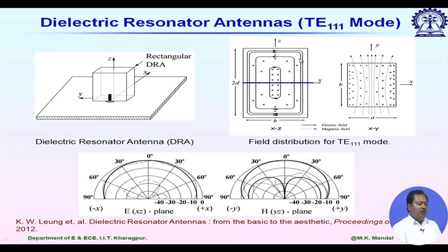Now, if I consider a full resonator, the ground plane is placed in the middle. For this full resonator, look at the electric field plot. It looks like one loop. Z is the top direction, and this DRA is placed in the XY plane. So, the magnetic field is perpendicular and forms a loop in the XY plane. You can look at the field plots. In the XY plane, the electric field is perpendicular, and the magnetic fields are parallel.